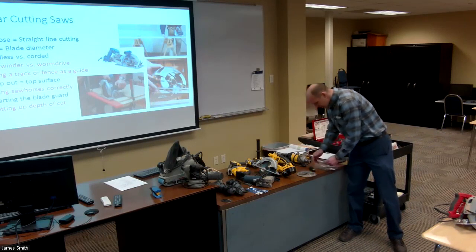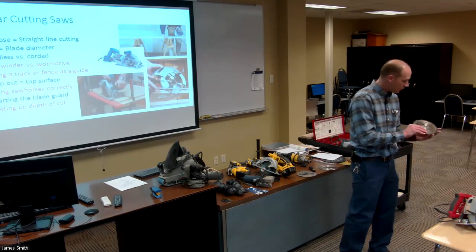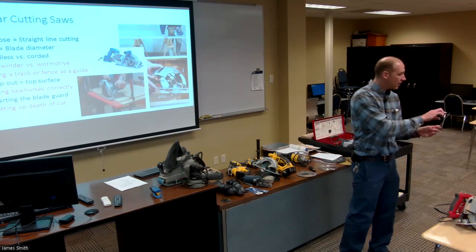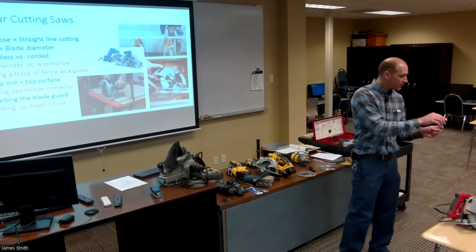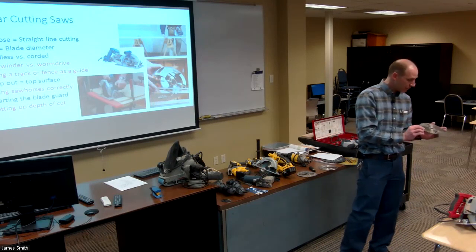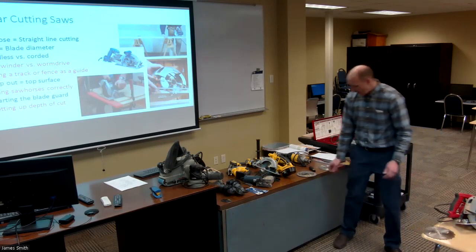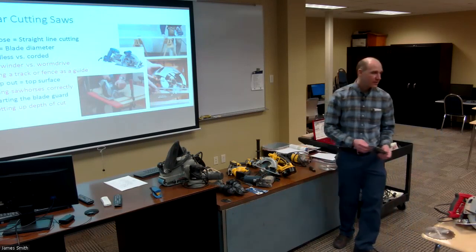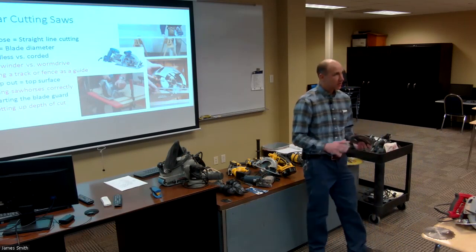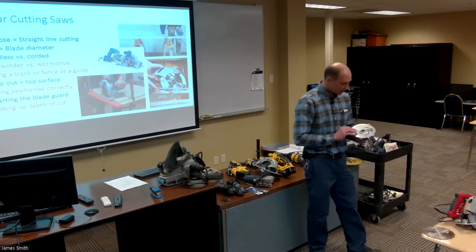But in situations where you're doing a lot of long ripping cuts, you might want to use a saw blade that has deeper throats or gullets, so that it can pull out those chips a lot more efficiently, okay? And so just understand that they have different types of blades designed for doing different things, cross-cutting or ripping, okay? And generally that has to do with tooth profile.